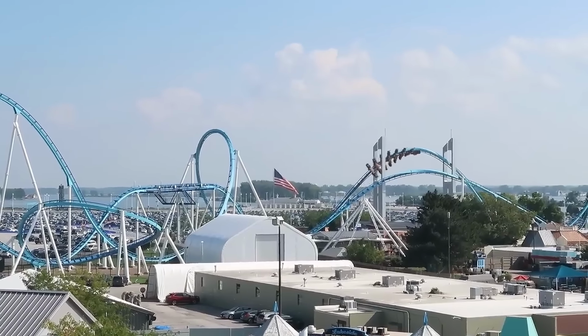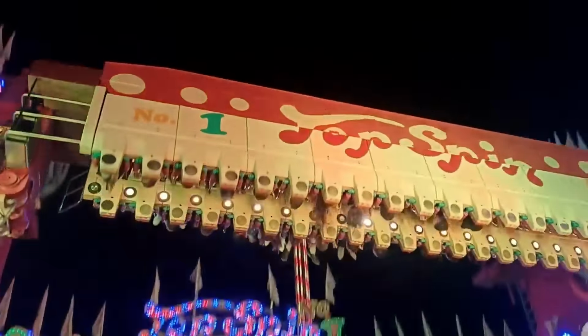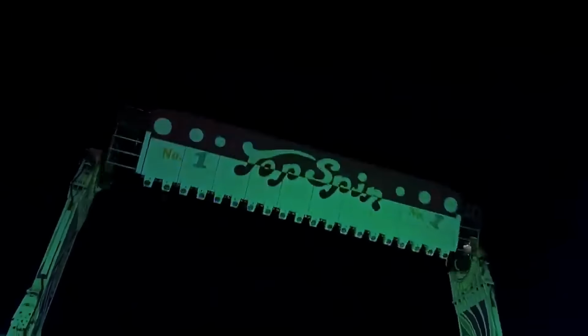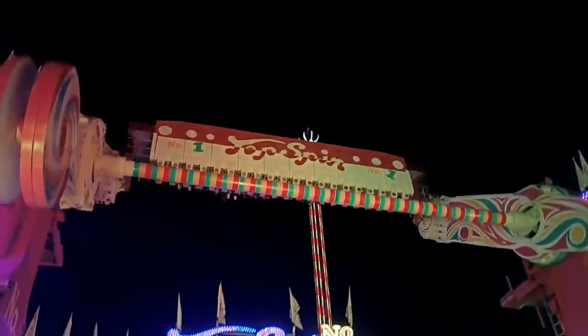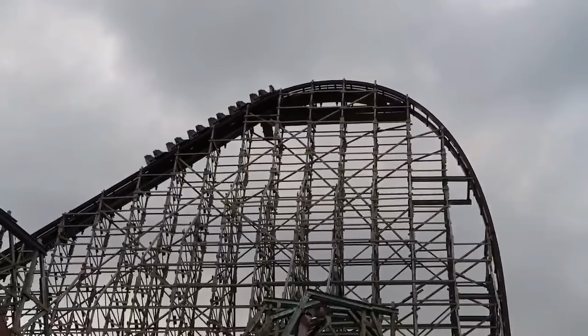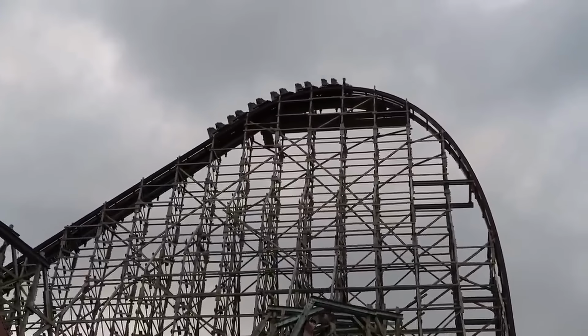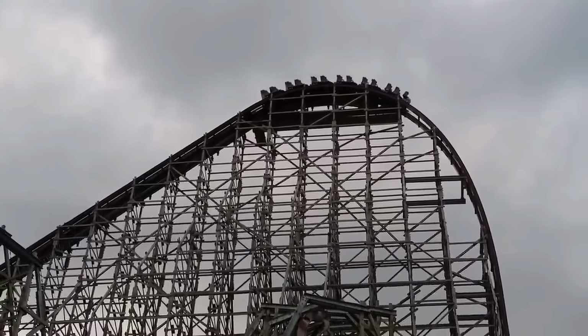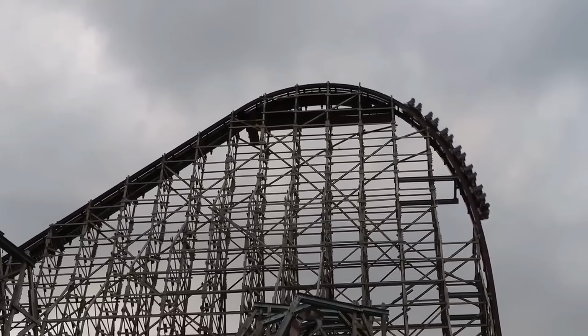An example of rides with 2 restraints are top spins, which use an over-the-shoulder restraint as well as a lap bar. Most Area 5 restraints opt for having 1 fail-safe restraint instead. Some examples of this are the restraints used on RMC coasters, which use 2 independent hydraulic systems to secure each lap bar. The area a ride's restraints must comply with is determined by this graph.